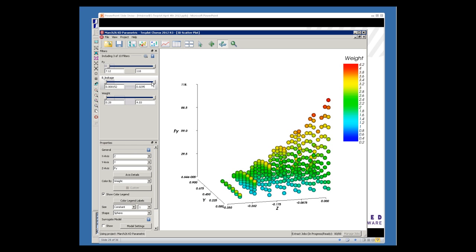I can go to the leakage table filter and begin to drop out the leakage and say, look, I just can't have some of these higher fields because the proximity of electronic equipment doesn't allow it. So I drop down the leakage field, and sure enough, it helps me to see that automatically there are several solutions that become disassociated. Same thing with weight. I know that weight, because of the aerospace application, was at a premium, and so as I began to put in the weight filter, many of these solutions began to go by the boards.